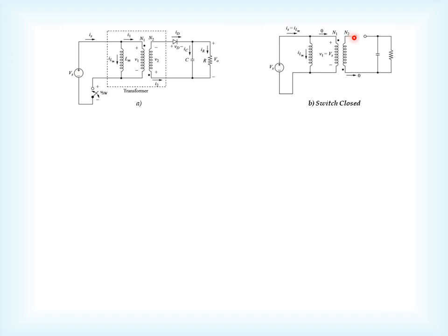If it is negative, the diode is reverse biased. A reverse biased diode acts as an open circuit. Therefore, the current through the secondary winding is zero. If the current through the secondary is zero, the current through the primary is also zero.